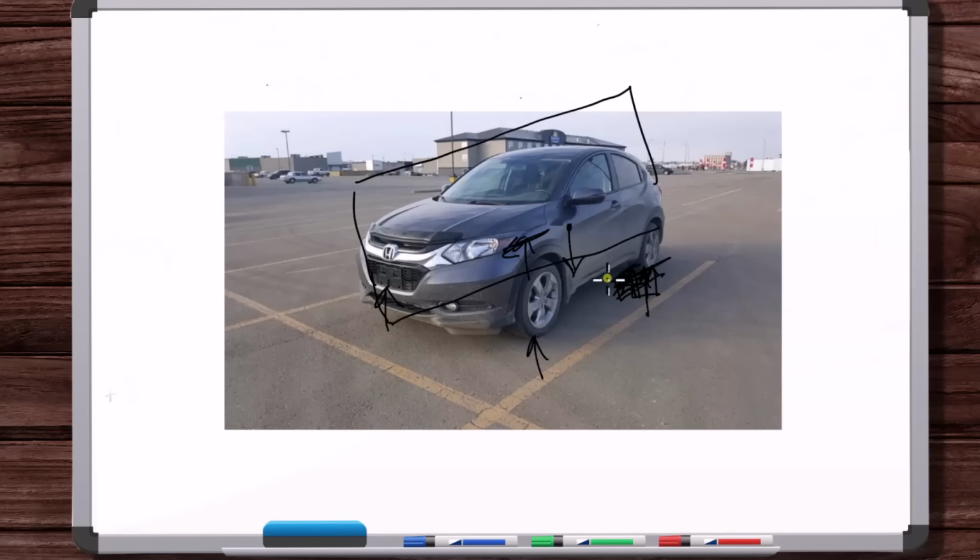We talked about how you can reduce a force, and that force actually is not even on the body itself. It's just a representation, right? The reduced force wouldn't be on any tire. It would be in the middle, but that's just a representation. That's the idea for a planar free body diagram. If you reduced all of the forces, point forces, distributed loads, couple moments, you reduced it all down, it would all fall into the center plane of symmetry. That's why you can do a free body diagram projected onto that plane of symmetry.